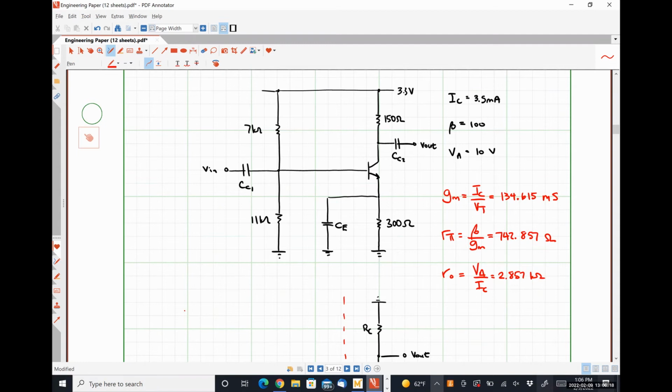That's literally how in modern analog electronics, like the processors in your computers and all that kind of good stuff, what do you think the supply voltages that they actually run at are? At this point, less than a volt. Less than 1 volt. Okay. So the only way to make that work is to not use physical resistors literally anywhere. All of the resistances are active load transistors. Okay. We'll talk about that much more in depth in 336.